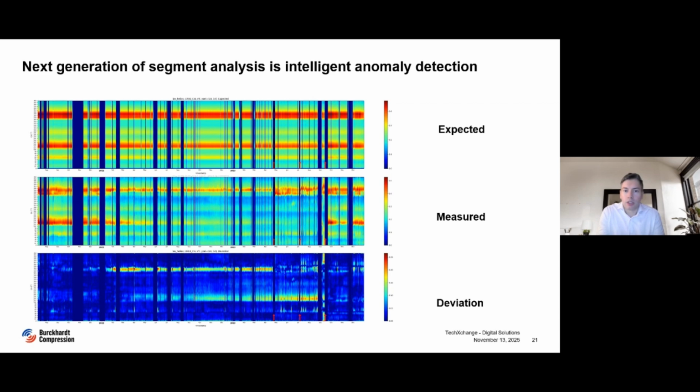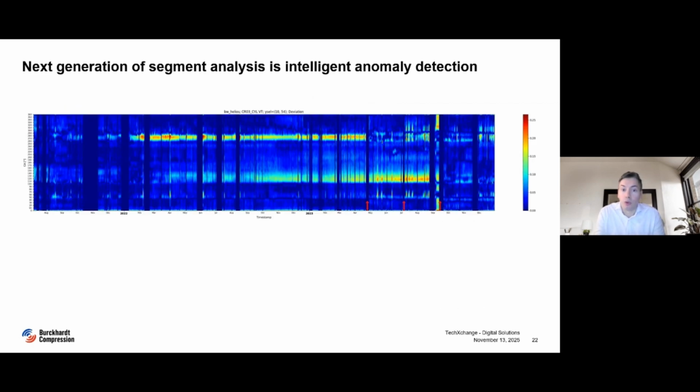This approach allows us to detect abnormal patterns early, patterns that traditional threshold-based methods would have missed, for example, a falling valve opening signal. As a result, operators can now focus on meaningful changes in the compressor behavior. And here, what are the key benefits? No manual threshold tuning, fewer false alarms, and also reduced maintenance efforts for the operators.